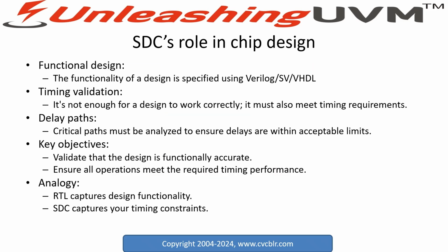So what's the role of SDC in chip design? The functional part of your design is captured using Verilog, SystemVerilog, or VHDL. Of course, as I mentioned, an IP that is written using VHDL can be integrated into an SoC, where the majority of the blocks perhaps are Verilog and some are SystemVerilog, some are VHDL. Mix and match is the reality of today. But what about the timing part? The timing specification is important because it's not enough for a design to work correctly. It must also meet the timing requirements.